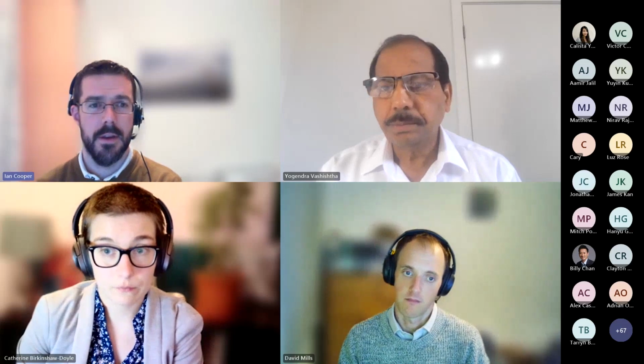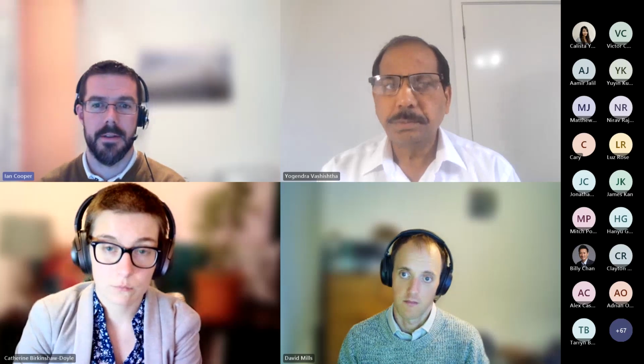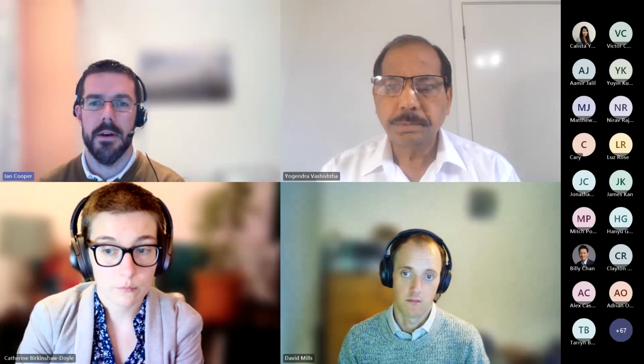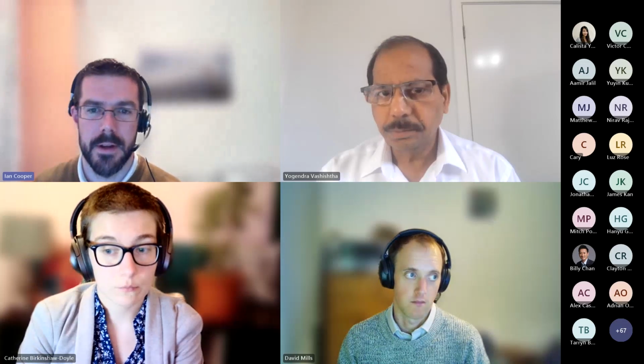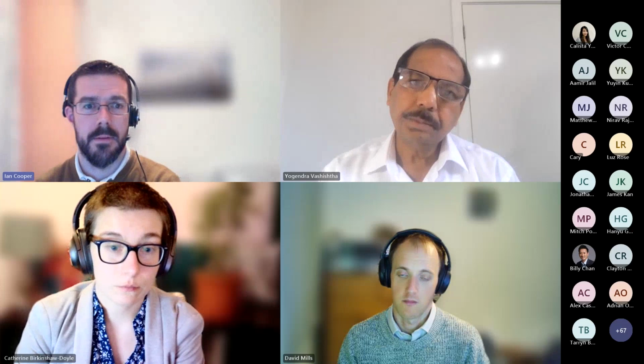So thank you, Catherine. It's something that we see in the UK, where there are commercial tariffs that are driving the behaviour of certain flexible demands on the network, which is reducing the diversity in some areas, and it is a concern for the networks here. And so it's something that we are definitely keen to model and to help people understand, and certainly we think it's easier and better in the tool that we have than potentially an ADMD approach, just showing a single peak value for the day.